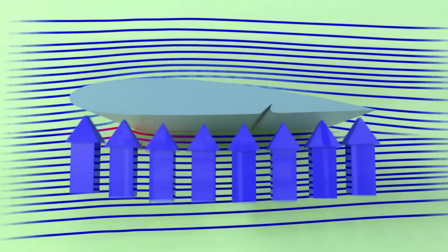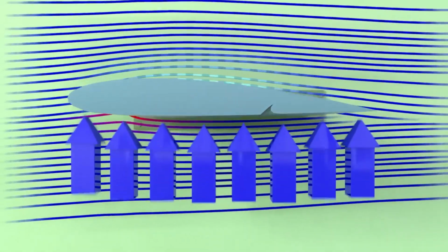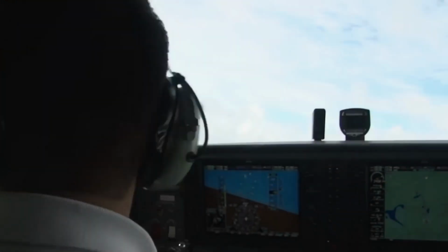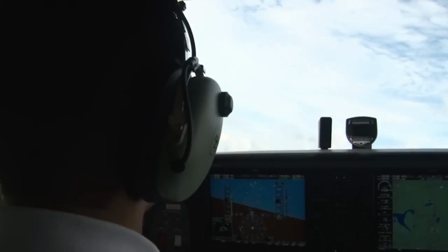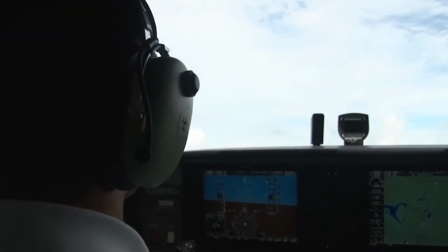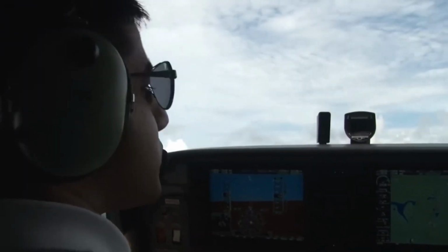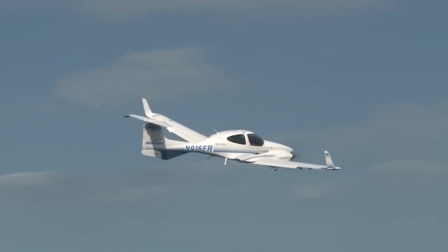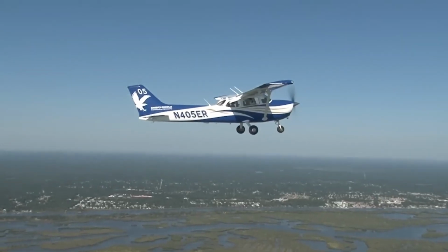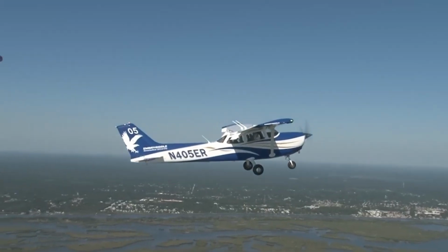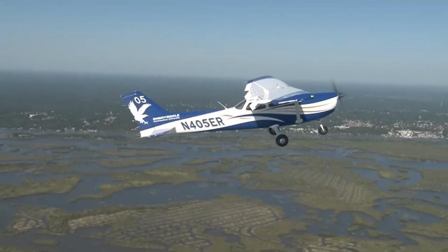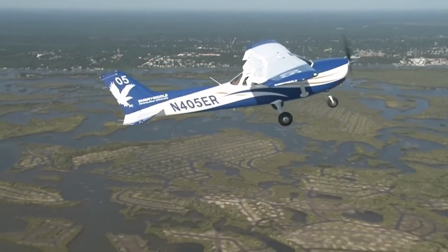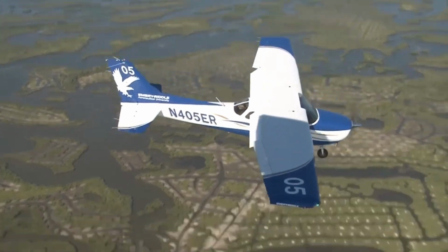Form drag. Form drag is the drag created because of the shape of a component or the aircraft. If one were to place a circular disc in an airstream, the pressure on both the top and bottom would be equal. However, the airflow starts to break down as the air flows around the back of the disc. This creates turbulence and hence a lower pressure results. Because the total pressure is affected by this reduced pressure, it creates a drag.